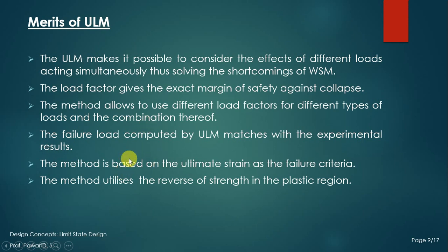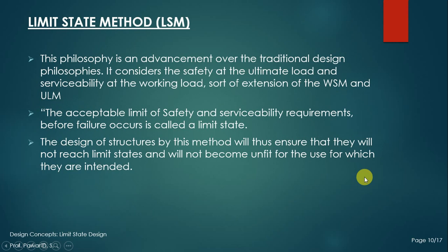The failure load computed by the ULM matches with the experimental results. The method is based on the ultimate strain as the failure criteria. The method utilizes the reserve of strength in the plastic region. And the last and important method is the limit state method.